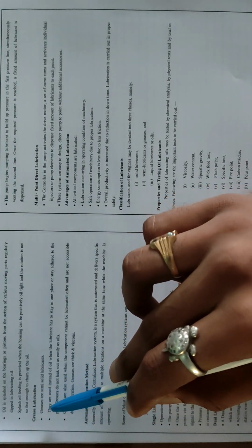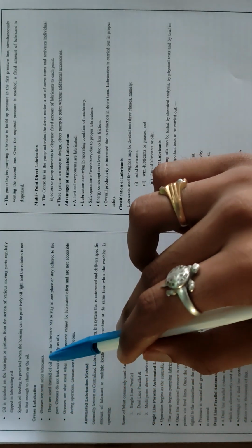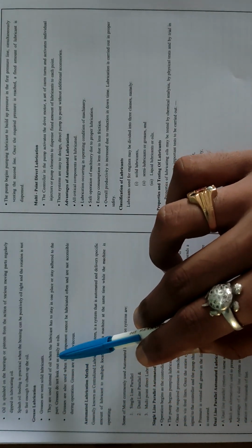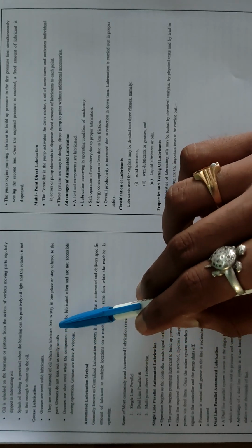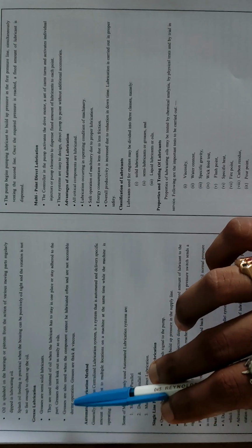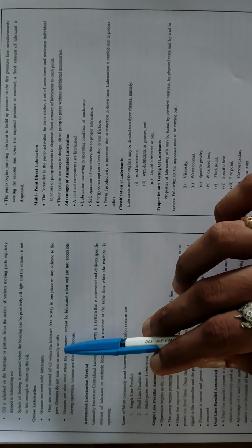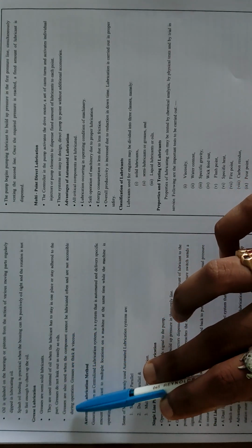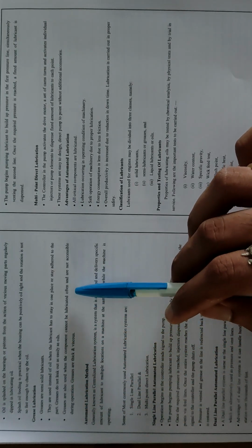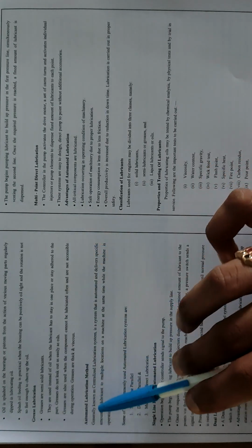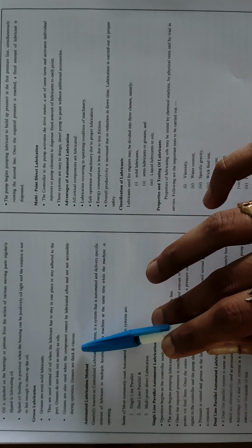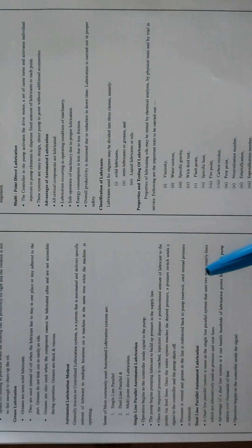Grease lubrication. Greases are semi-solid lubricants. They are used instead of oil when the lubricant has to stay in place or stay adhered to the part. Greases do not leak out as easily as oils. Greases are also used when the component cannot be lubricated often and is not accessible during lubrication. Greases are thick and viscous.